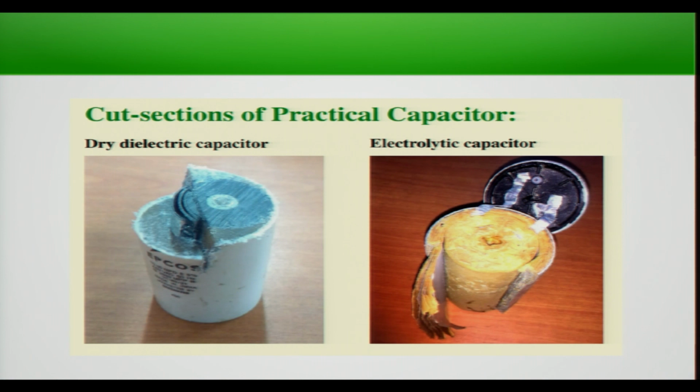So, in our imagination we think that a capacitor would only be a parallel plate capacitor, but effectively any two metals which are separated by a dielectric will have this capacitive effect. In fact, even as I mentioned some time back, a real life inductor also has a capacitive effect, because parts of the metallic wire are separated by some dielectric or air or some other material. So, this is in fact how a real life capacitor looks like.